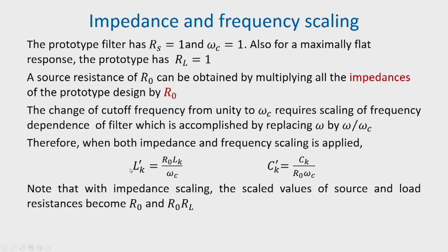So, this is the series element we used, and the scaled value of the capacitance C k becomes C k by R naught omega c.